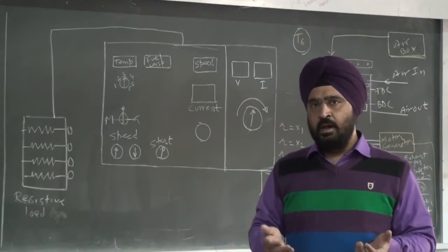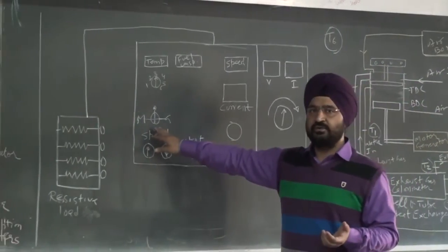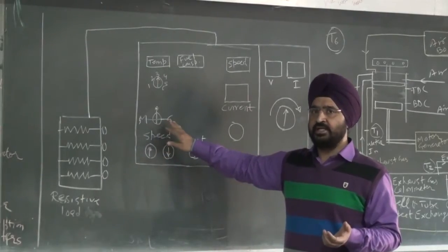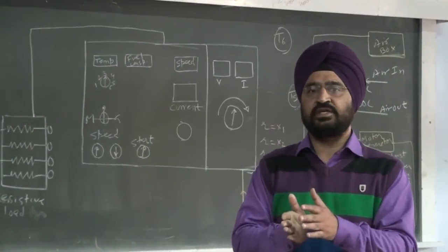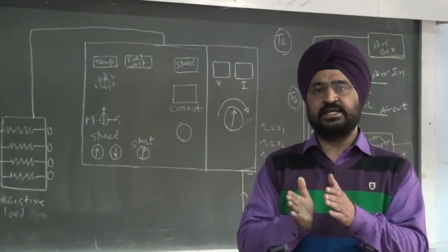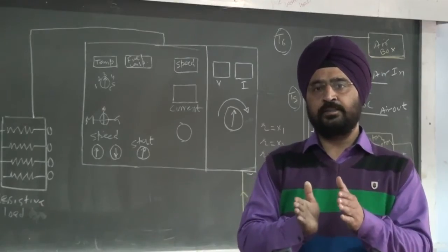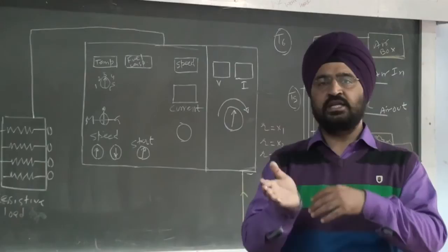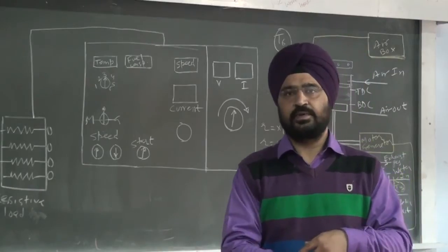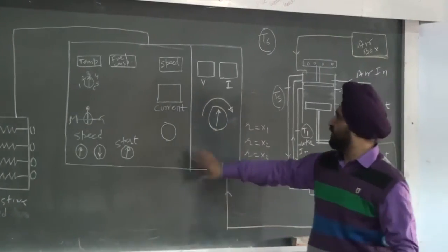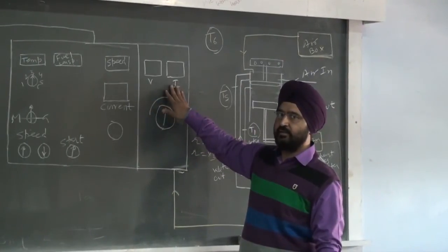at the same RPM. So the engine will run in motor mode and in generator mode, at the same speed. If your engine testing is running at 2800 RPM, 3000, then after cutting off the petrol and the spark plug, in the reverse mode it should also run at 2800 and at 3000 RPM. Now in the testing, you will be able to get the measurement related to the voltage, and you will also get the measurement related to the current.